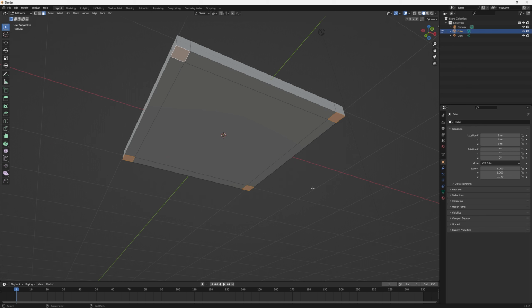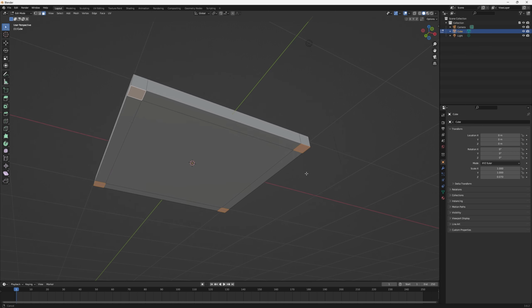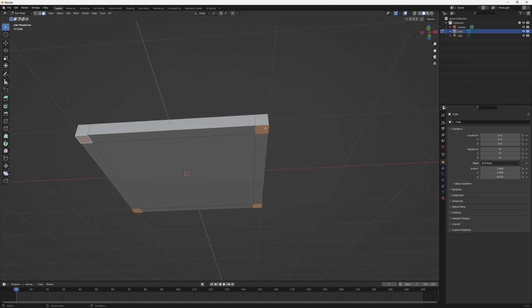So extrusion, as I mentioned in class, is one of the most common operations or functions in 3D modeling. Extrusion basically allows you to make a copy of this face and then pull it down, and by pulling it down, it will create new polygons along the way. So let's select all of these four faces, and then the extrude function is here. Most of the common functions you can find on the left toolbar. This function says extrude region, and the shortcut, as you can see, is the E key, the first letter of the word extrude, the E key.